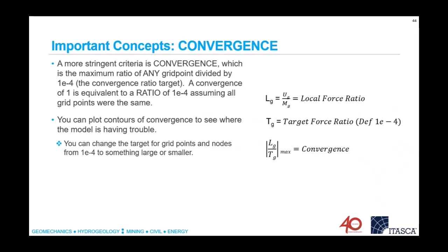And it also allows us to say that, okay, I see that this part of the model, which I'm actually not interested in, keeps my model from converging. It's not equilibrating there. I don't really care that results may be slightly more inaccurate in that part of the model. So I can specify a larger convergence criterion there and just arrive at the solution faster, while everywhere else, it's also accurate and it's fast.